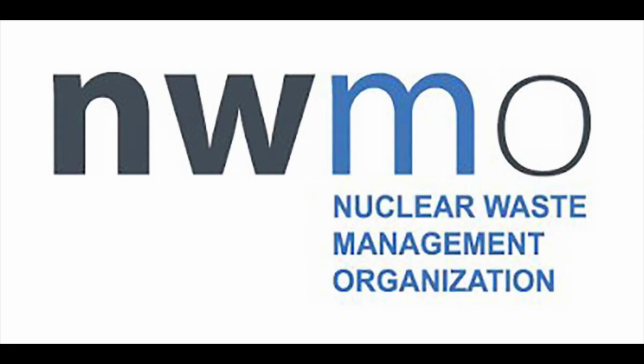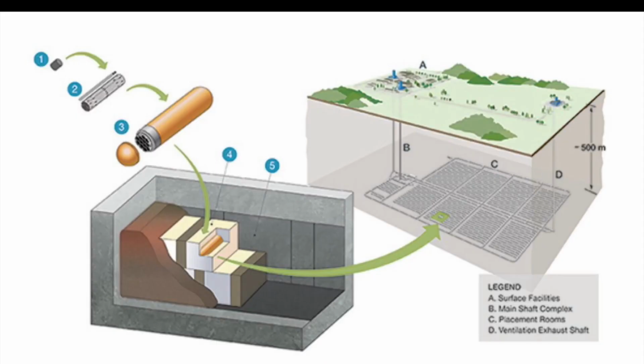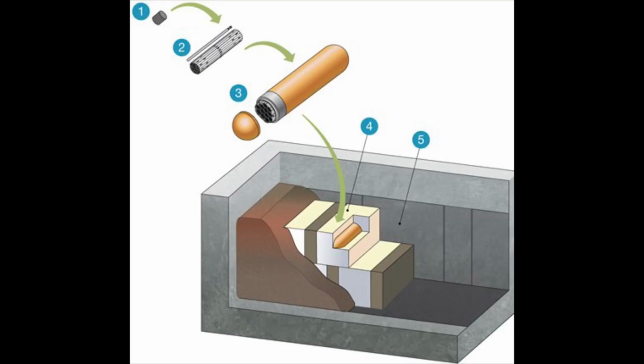The Nuclear Waste Management Organization, which is responsible for Canada's nuclear storage and management, has proposed a deep geological repository as a long-term dry storage site of used fuel. Within the repository, there is a multi-barrier system composed of both engineered and natural protection, specifically an MX80 bentonite clay buffer sealant surrounding the copper-coated used fuel containers, all of which are further protected by the geosphere. Both sedimentary and crystalline rock formations are being considered as potential host rocks.